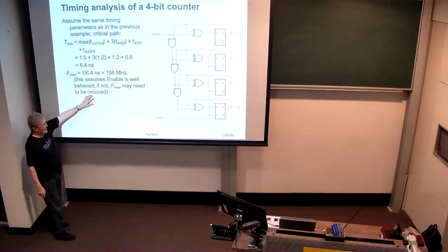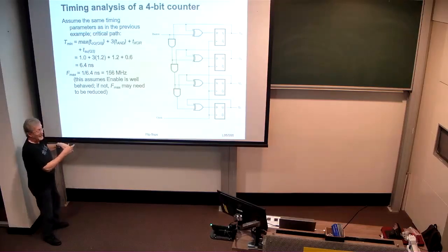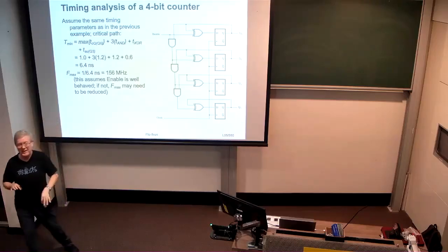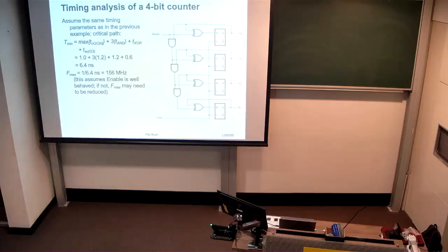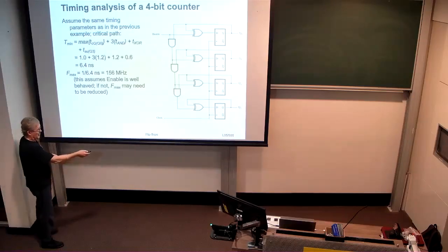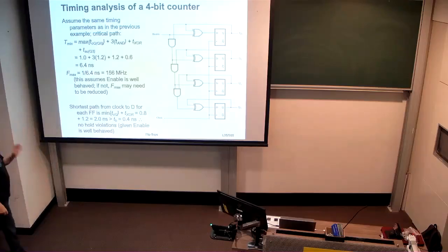This is an important caveat. We're assuming here that the enable signal is well behaved and that it doesn't toggle at some stage to upset the apple cart, so that setup time isn't satisfied down the bottom here. We'll have a little think about that in a moment.